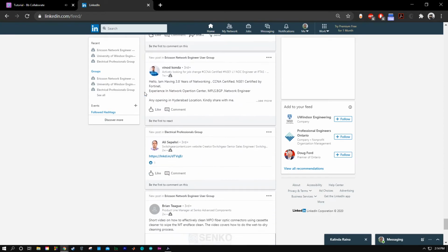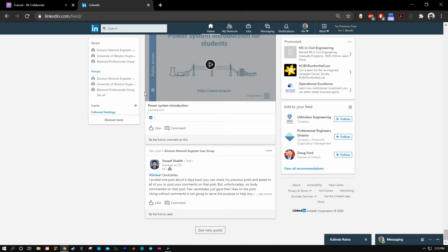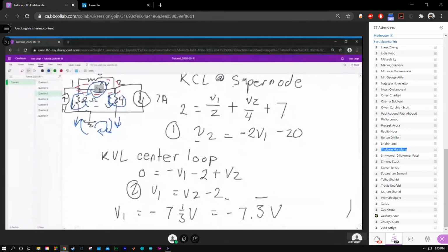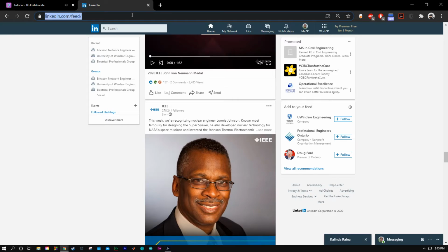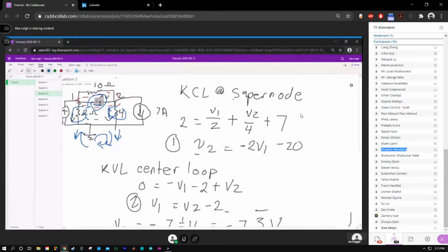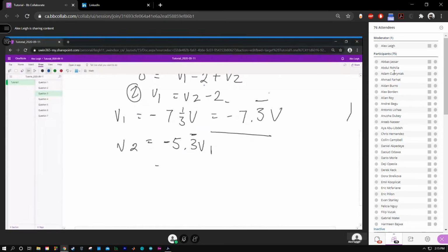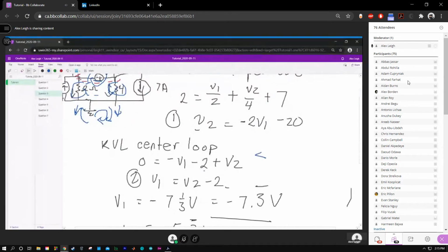This one here, when I'm going through the rotation, I'm entering the negative terminal of the voltage source, which means that I have to define it as negative 2 volts, because it's a positive 2, but with respect to the proper direction. This one here, I'm following the direction of the current we defined for V2, so I'm calling it positive V2. And that's how I end up with this: 0 is the sum. Here I have a negative V1, a negative 2, and a positive V2. And that's where I got that equation right here from.